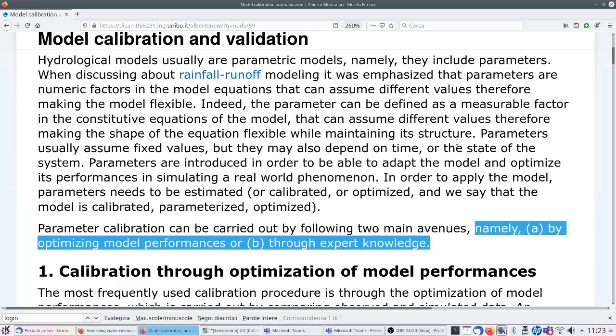One is numerical, like, okay, I have a model and I have a code that is running the model as we did in our exercise with iMod. We just ran the model to find out what is the best combination of parameters. So this is a numerical way. I may even ignore the process. Calibration, numerical calibration, is the same process, no matter if you want to describe the growth and the number of potatoes, or you want to describe water resources availability. Calibration is the same process. You just run a mathematical model independently of the process that you are describing, and you find by numerical experiments the best combination. Expert knowledge, of course, is based on your knowledge of the problem, and by using your knowledge, which may derive from measurements, from observations, you guess the parameter values.